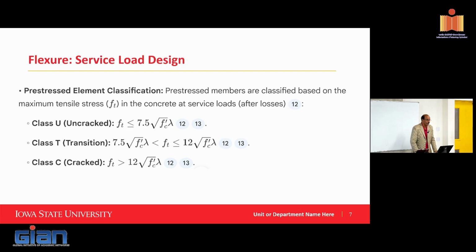Your stiffness can drop by 50% if it's a cracked section, depending on the amount of axial force, or if you have any axial force on the member. So in some design calculations, that becomes a critical piece. And then, as I mentioned yesterday, typically prestressed concrete is designed to be crack-free. So you do all of the calculation accordingly, but because of your erection process, you end up causing cracking, then obviously your stiffness has dropped and other things will follow.